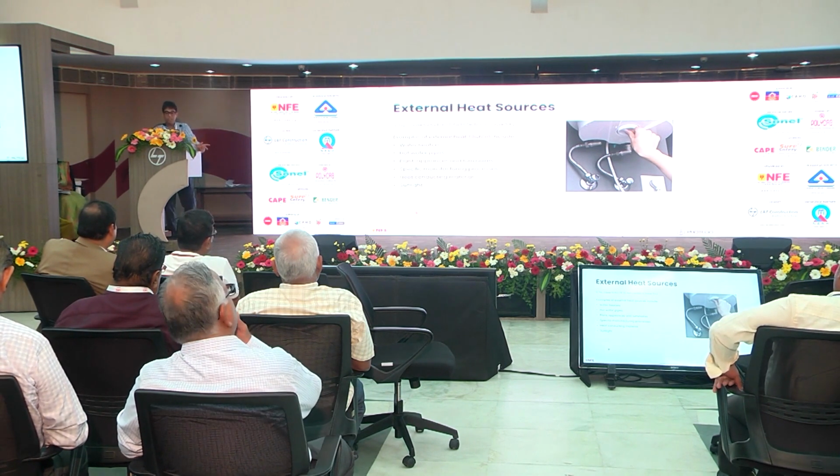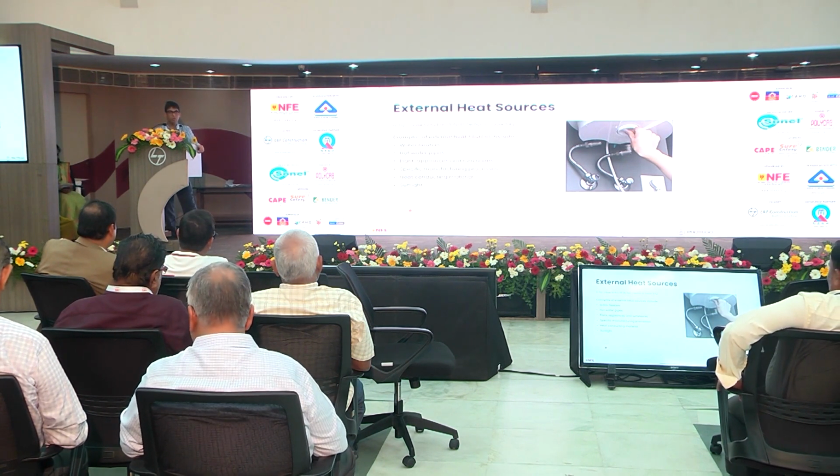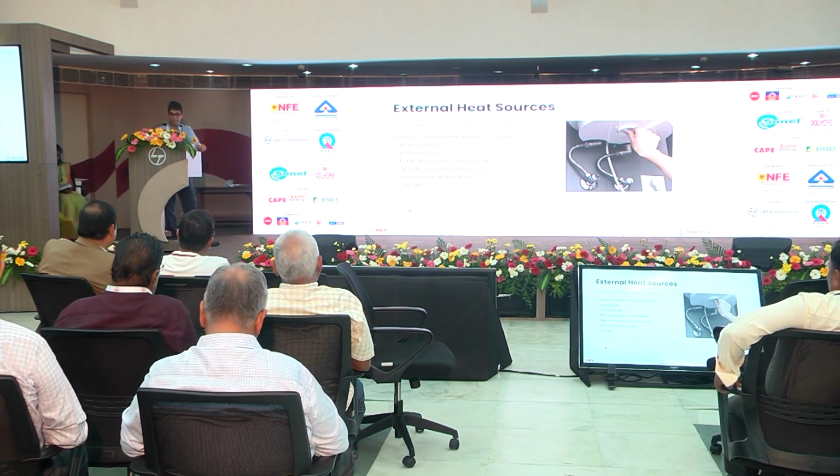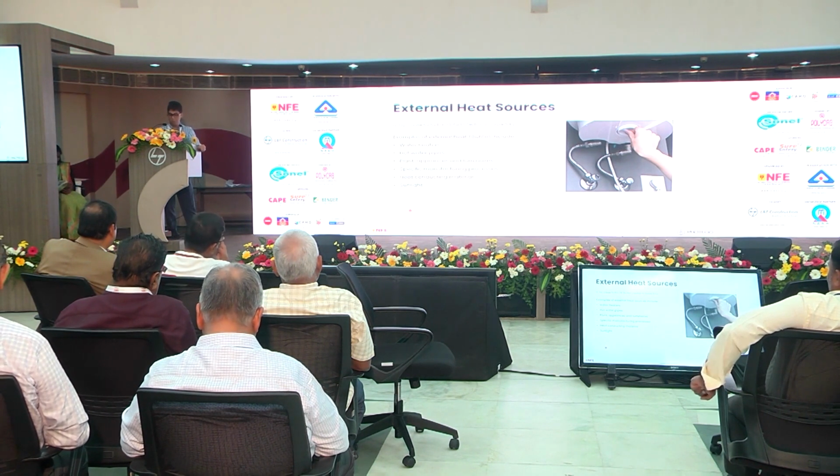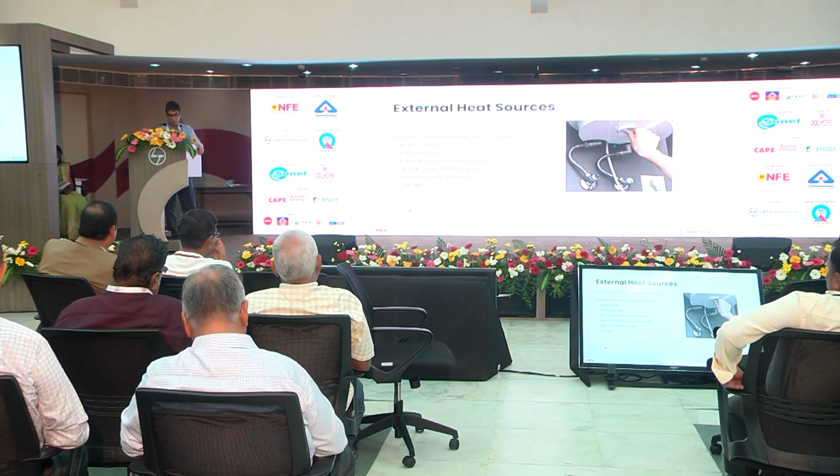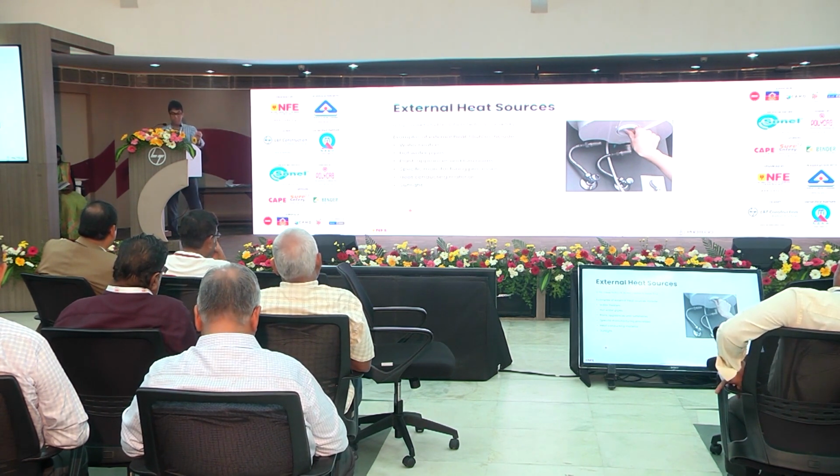Even sunlight is a big one here, because we think about sunlight as UV rays degrading insulation, but even constant exposure to sunlight will raise the operating temperature and could take temperatures beyond the temperature the cable could withstand.